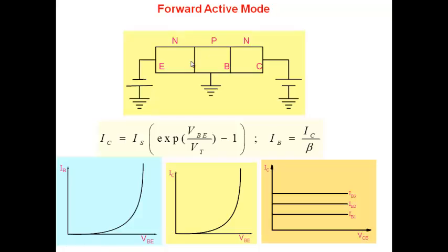So as you increase the diode voltage, the current linked with this diode increases exponentially, and the current elsewhere also increases exponentially. So that's why you see this exponential behavior here. And we saw transistor action: the current doesn't depend on the reverse bias that you apply on the other junction. Whether you apply more or less, the current is sort of independent of it.